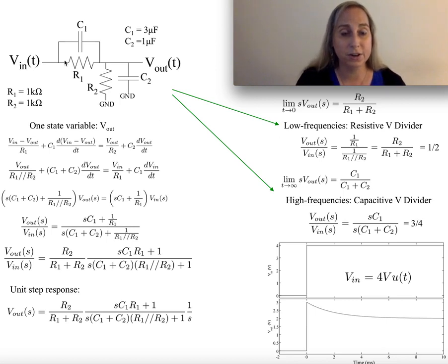And you think to yourself, well, it's an RC type circuit, so I've got a capacitor here. So I just simply say, all right, I probably have a sense that there's two R's here. Maybe there's a C. The C gets added in somewhere. And I could get some interesting time constant that maybe is related to, I don't know, the parallel combination of the two R's times the sum of the two capacitances. And interestingly enough, if you pick that out as your time constant, that works about right, it turns out. We'll eventually be able to see down here that our core time constant really is the sum of the two capacitances times the parallel combination of the R's.